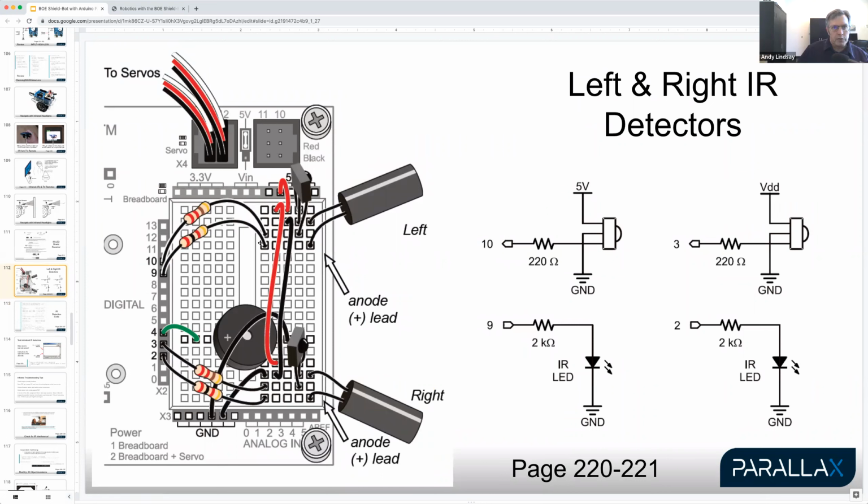So the first thing I would do is check, you're getting all ones. So check first that your 5 volts is going to the top row. And then you've got a jumper from that top row to the topmost pin of the lower 3-pin infrared receiver.